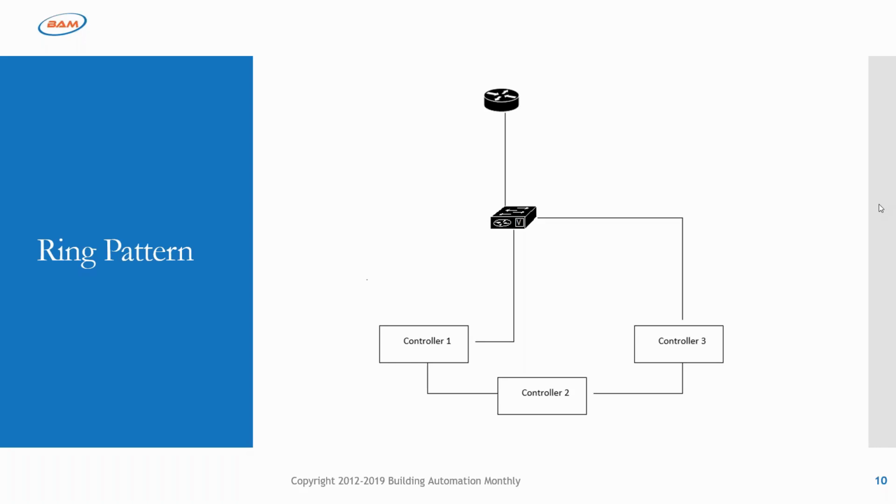And what if controller 2 goes down? Does it communicate with both sides of the ring? I think I kind of answered that. It will notice that the loop is ending, and once again, this depends on switch setup and manufacturer setup, but it will open up the other port most of the time.